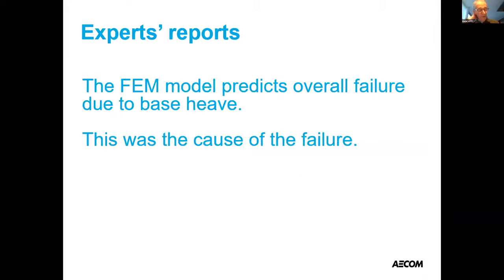And base heave is when the soil at the bottom of the excavation is so soft that it rises as the embedded section of the wall beneath excavation level is pushing forward and trying to develop passive pressure. Now, this site location was a reclamation which had a very, very thick clay deposit, marine clay, and sand fill on top of it. In fact, there was evidence from piezometers installed before excavation that there was still some residual positive pore pressures from the reclamation, and that the clay wasn't fully consolidated. So the clay was relatively soft at formation level. It had a cohesion of about 20 kPa, which is rather like toothpaste, a little bit firmer than toothpaste, not much firmer.